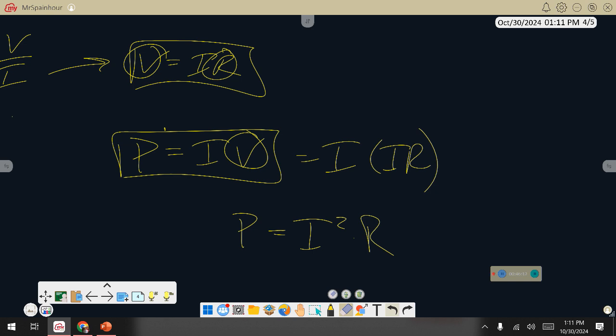This is going to be specifically helpful when you know the resistance has stayed the same and the current has changed by a certain amount. Say I double the current. What effect should that have on power? Well, you can see here that if the resistance stays the same and the current doubled, then power should go up by 4. Now, you could get that exact same line of logic by looking at these two equations, because if my resistance has stayed the same and I want my current to double, what do I have to do?